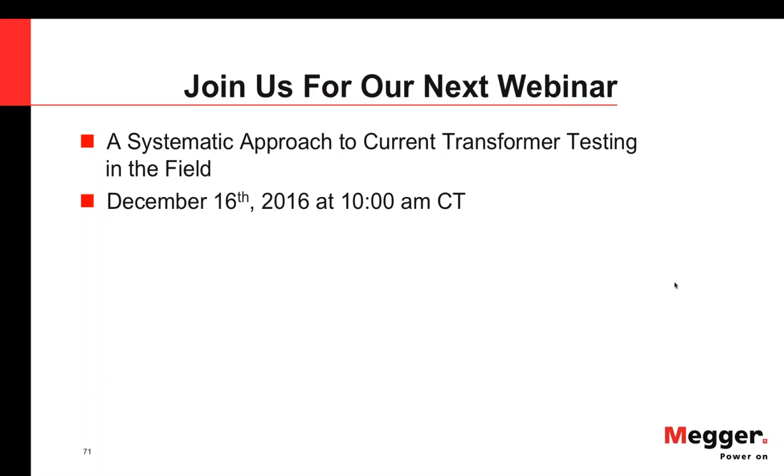One of the things about solar tiles is they have very low impedance. So when the sun changes, when you have a change in magnitude from a cloud or even just pollution, it's not just visible light that affects these things. Their response is very fast, almost instantaneous. So you can get transients off these, and these transients can be continuous for a while, depending on what's happening with the light. And it's believed that these transients may be causing damage to some of the electronic equipment that is out there.